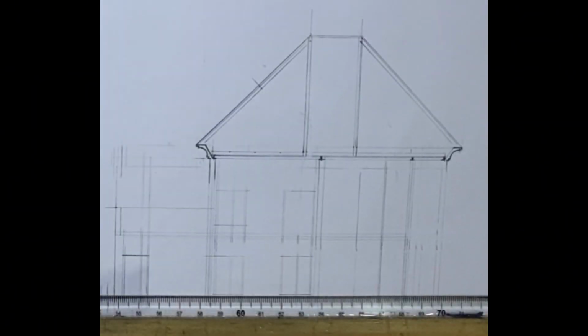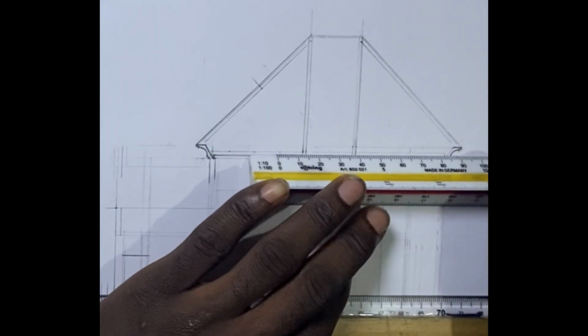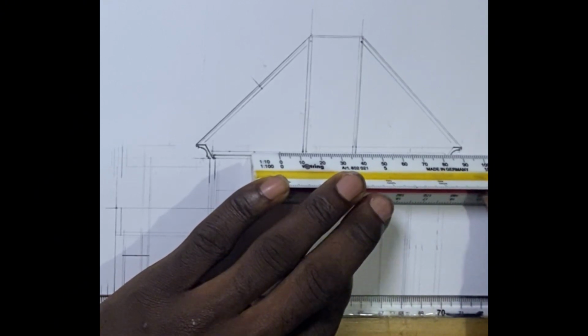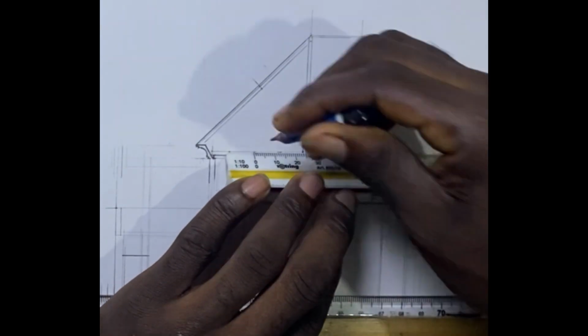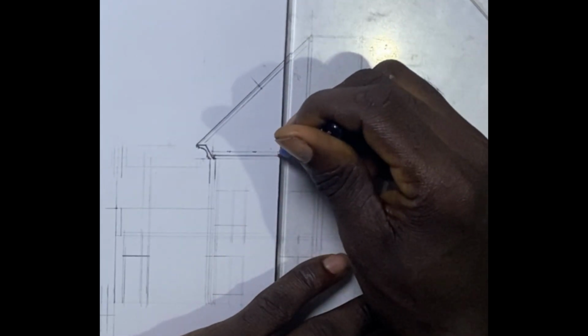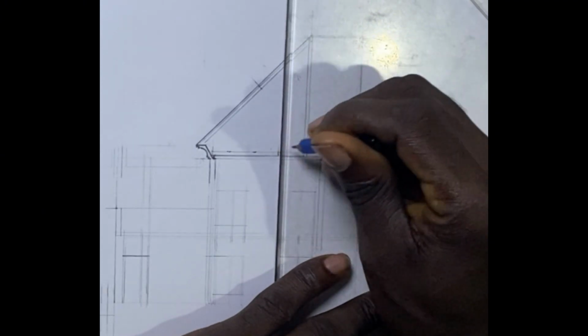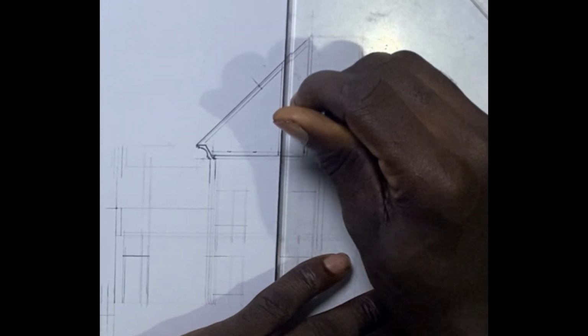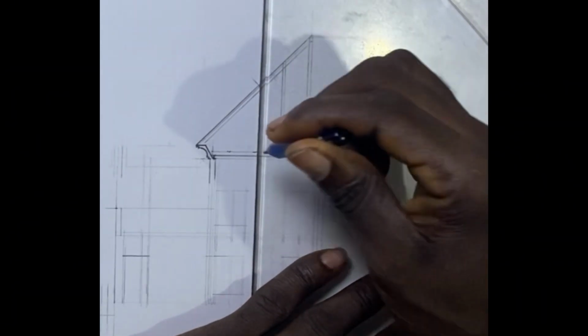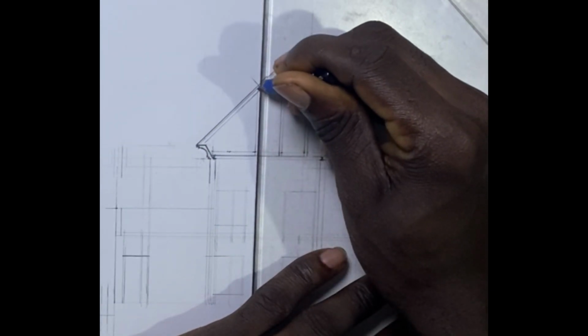The strut, unlike the king post, is 50 by 100 millimeter, and in this case we are seeing that of the 100 millimeter, unlike our king post which is 150 millimeter. Like the king post, the struts are also nailed on our rafter and our tie beam, so you can do it lightly at first. Then once you are done, we are going to thicken it out.